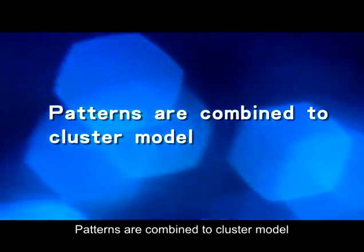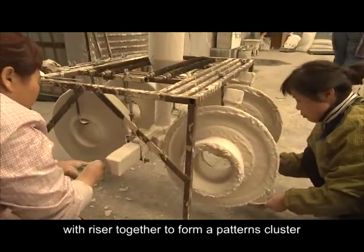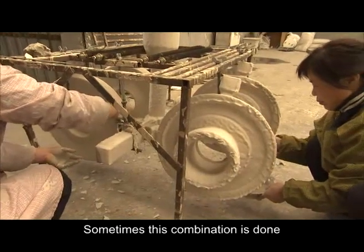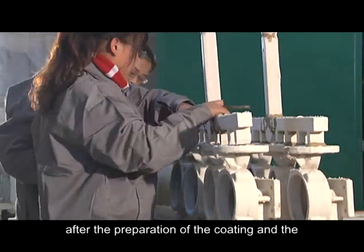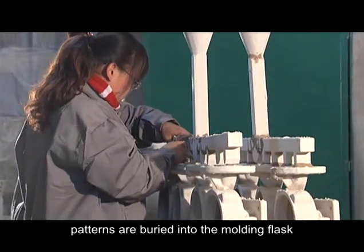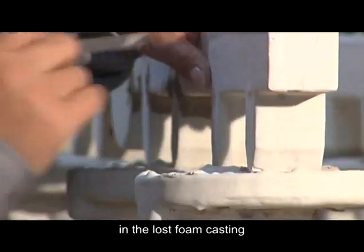Patterns are combined into a cluster model. This step is to combine multiple foam patterns with a riser together to form a pattern cluster. Sometimes this combination is done before brushing the coating. Sometimes it is done after the preparation of the coating, when the patterns are buried into the molding flask. This process is a necessary procedure in lost foam casting.